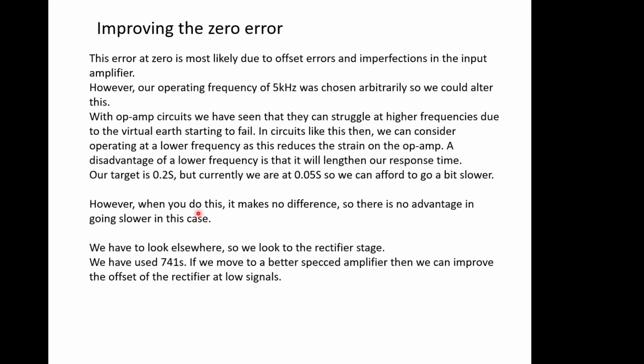So I did that, and actually it makes no difference if you go down to 2 kHz or so. So there's no advantage in going slow in this case. But the advantage is in the simulator you can try these things quite easily and see what the answer is. In a circuit, building it becomes a bit of a problem. It takes a lot of time. So the input stage is probably all right.